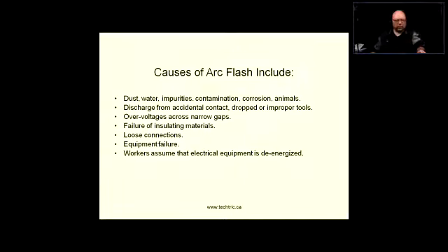Whenever you're working on equipment that is usually energized, you have to make sure that the equipment is de-energized. How do you do it? Well, there are certain procedures that you are required to perform. You have to go to the circuit breaker or wherever the disconnect is, and disconnect the power to whatever device you are going to use.